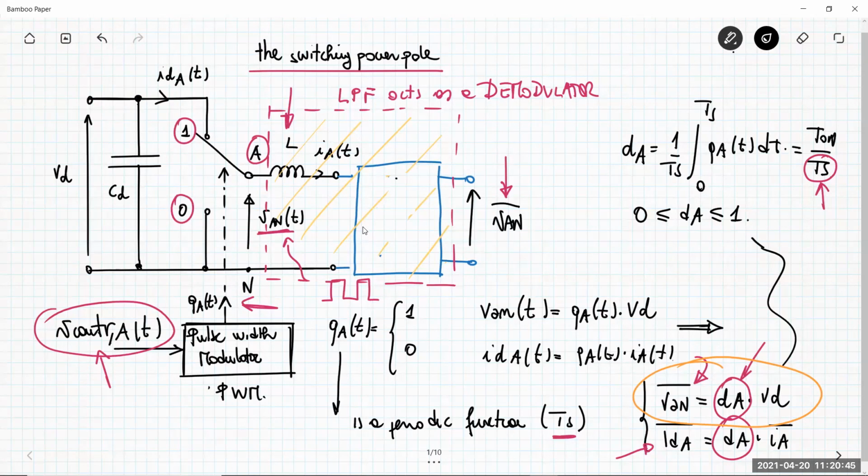This action in motor application typically is performed by exploiting the reactive characteristic of the motors. So that means that here I typically do not add anything. I have a motor connected at the output. The motor has some capacitive, reactive, resistive characteristics. Then typically the demodulator relies on the reactive parasitics of the motor.